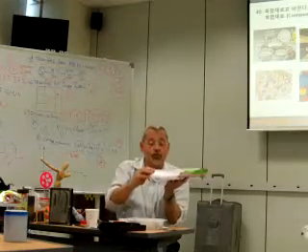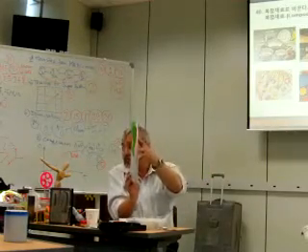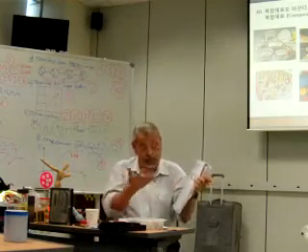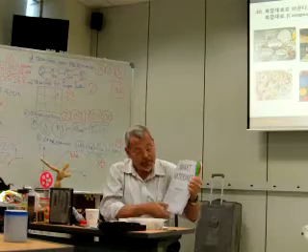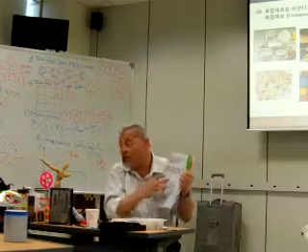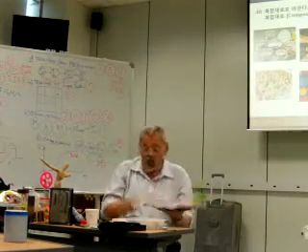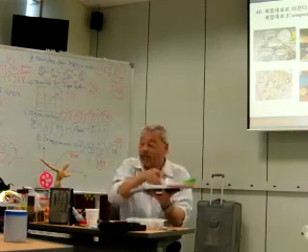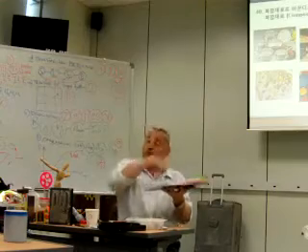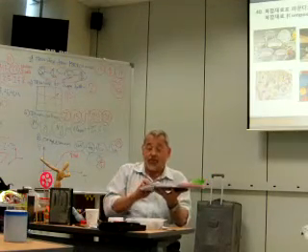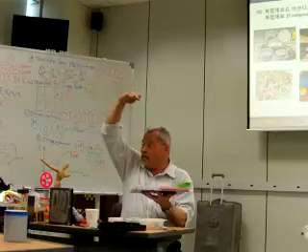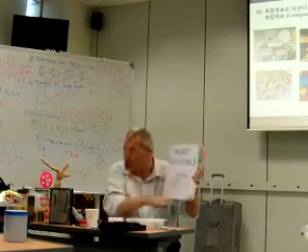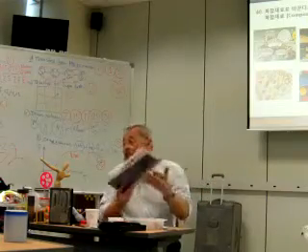After this, according to technology, it is necessary to turn over the PCB, and your ink can fall down, and it will damage the PCB. And when we deliver thixotropic materials, we have small viscosity, but when we remove mechanical stress, viscosity jumps up, yeah? And you can turn it, and your ink will not fall down. And it is a smart material also.